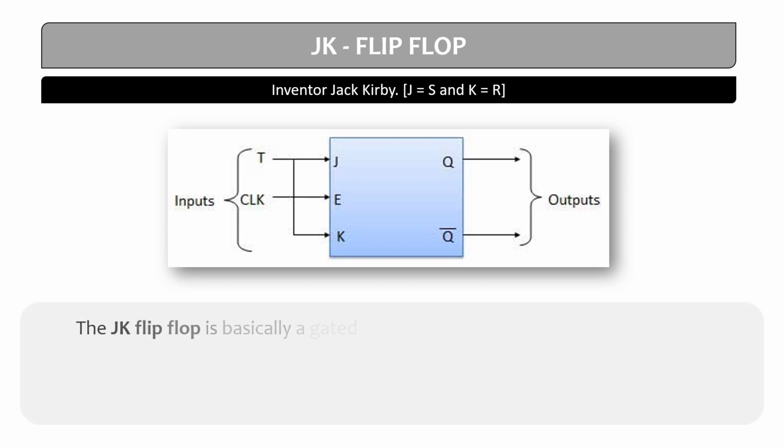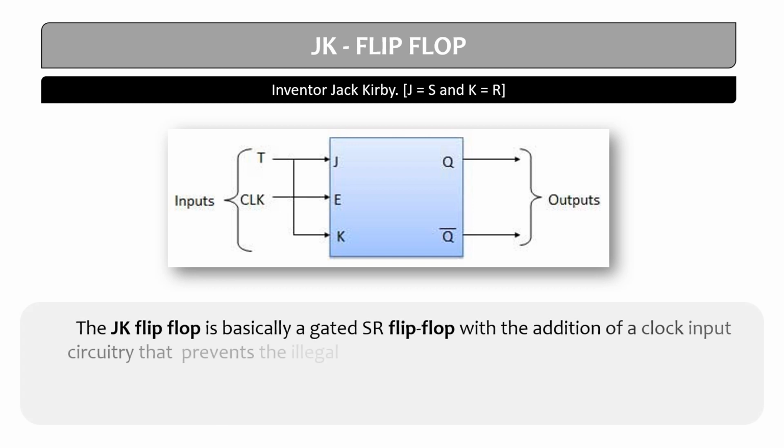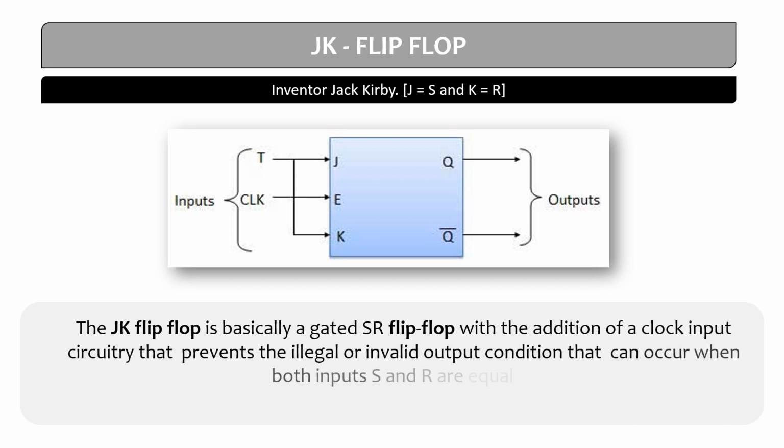as you know, the JK flip-flop basically is an RS flip-flop with its outputs Q dash and Q ANDed together with J and K respectively. Now we know this. And this type of JK flip-flop normally has no special name, because we call it JK, and we understand that J is set and K is reset. And one thing we need to note down here, that the connection between the outputs and the inputs to the AND gates determines the input conditions to the R and S, especially when J and K both are 1.